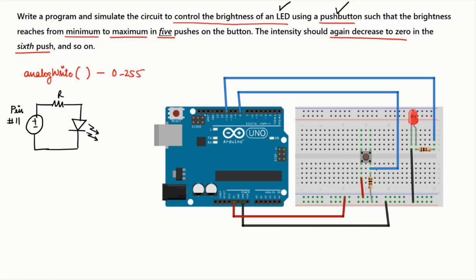And we also have an independent circuit, a separate circuit, connecting the push button with pin number 8. So before that, we noticed that the push button has one terminal connected to 5 volt and the other side connected via a resistor to the ground. Right? So it's a circuit like this.